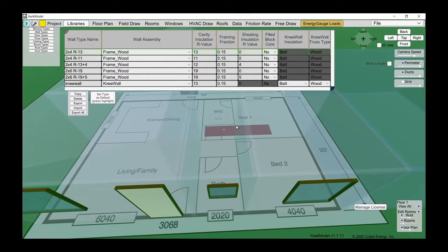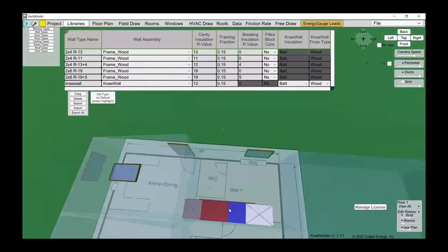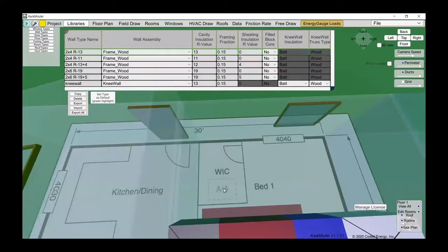Okay. And then interesting question. Can a door be drawn in the ceiling for an attic hatch? I don't know if we have anything. No, actually, that's a good question. So here's your attic access here. Most attic accesses are sheetrock with the same insulation, if they're insulated. In California, there's a rule that says your attic access has to have insulation permanently attached to it, so that when you open your attic access, that piece of insulation doesn't fall off and stay off.